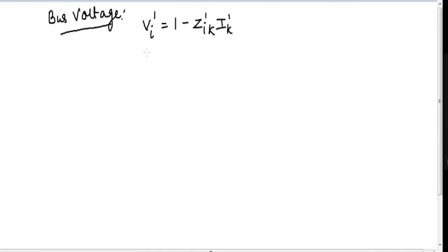क्योंकि ये थ्री फेज फॉल्ट है और थ्री फेज फॉल्ट में जीरो सीक्वेंस और निगेटिव सीक्वेंस ये दोनों ही सीक्वेंस रहते नहीं हैं, इसीलिए हम ये दोनों सीक्वेंस को कैलकुलेट भी नहीं करेंगे क्योंकि जीरो ही आएगा इसका आंसर। ठीक है, so what we will start with, we will start with bus number 1. So I am going to calculate here for bus number 1. Rest of the three buses you have to calculate.